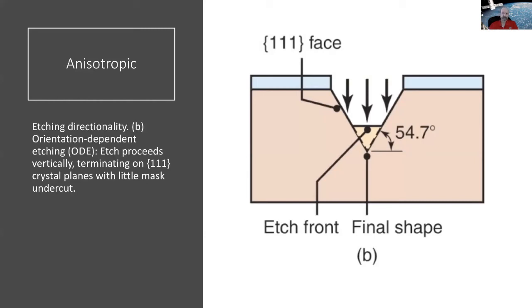The 100 plane etches at about 1.2 microns per minute at 80 degrees C for potassium hydroxide at about 30% concentration. So it's etching down, down, down, but it etches the 111 plane more than 1/400th slower. So effectively, it doesn't etch the 111 plane. It follows the 111 plane down, and you can see it following down.